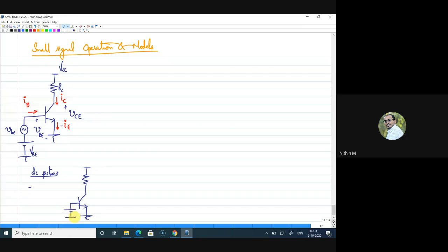We have a VBE voltage here. That's all. So that will give you a DC current IB. Now here will be your DC voltage VC that is established through VCC and this RC, and this will be the collector current IC, and the total emitter current will be flowing here, right? So the relations we know, and VB we are directly giving, and the voltage here is established as, so what is this voltage VC? VC is actually VCC minus IC into RC. These are the DC conditions, right?